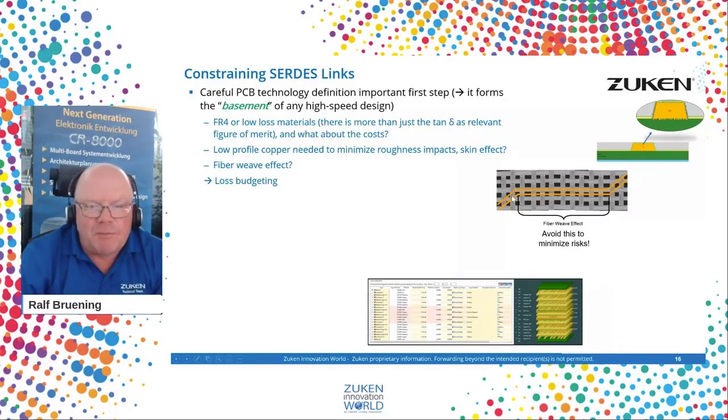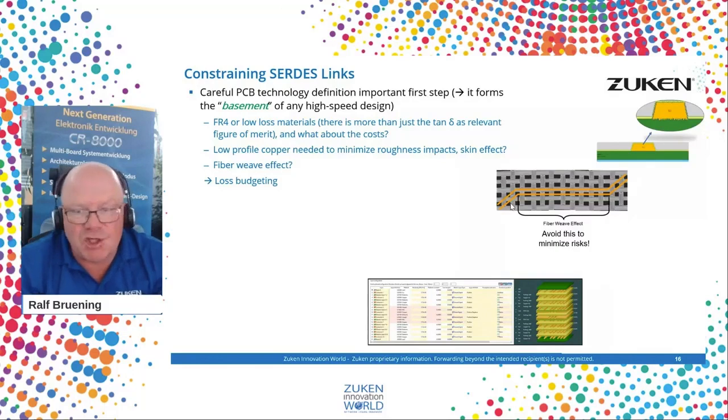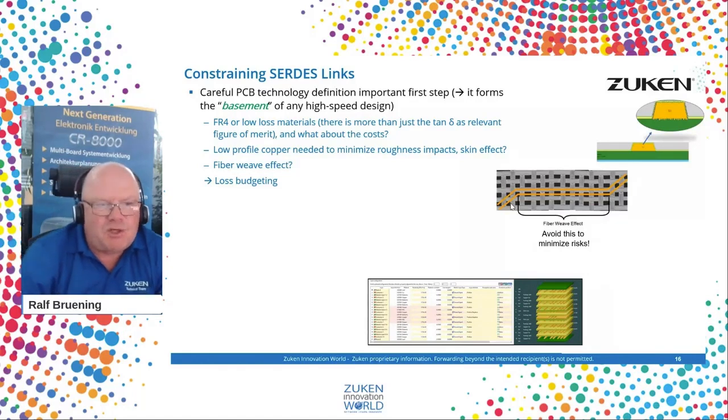So we have a differential pair, where the two legs of the differential pair are exposed to two completely different electrical conditions. So this will change the velocity, this will change the delay, this will introduce a phase shift, and you will have a differential to common mode transformation. So at the end, you may create a pretty bad EMI antenna by that situation.